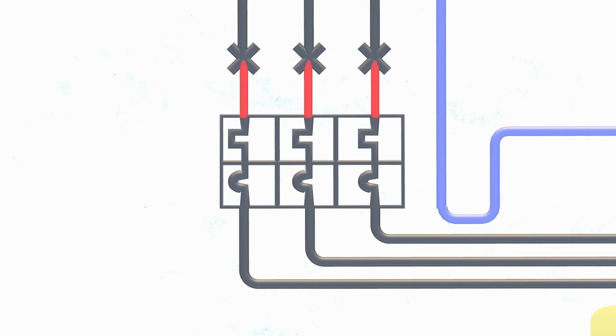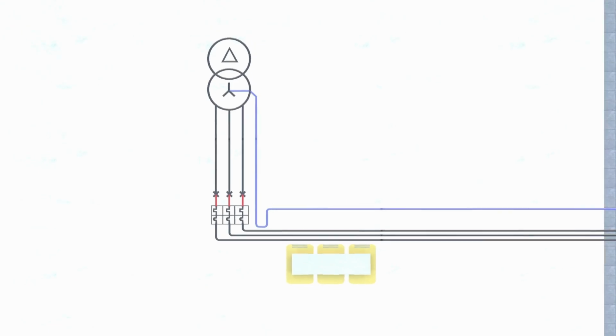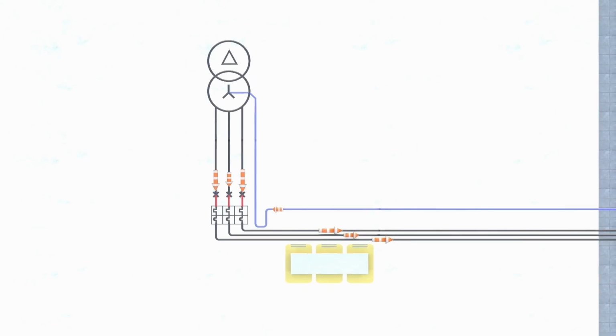In the individual phases, different currents are formed, represented here by arrows of different sizes, which lead to an asymmetric load. As a result, a current component is generated on the neutral conductor. This current flows in the opposite direction back to the medium voltage transformer. Some of the backflow can also follow the route through additional grounded system components apart from the original path it took. All in all, this leads to electrical losses that don't bring any benefit, but still have to be paid for. Ideally, these are zero.